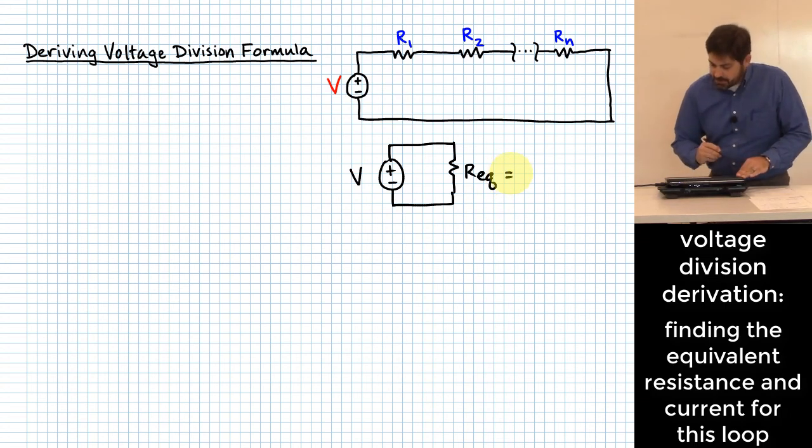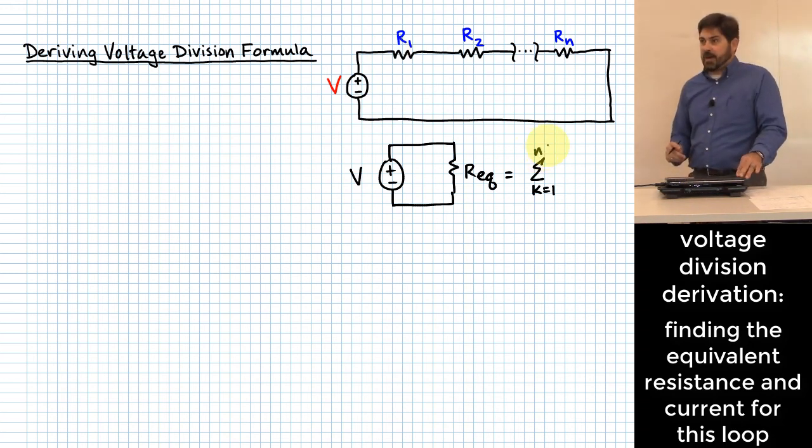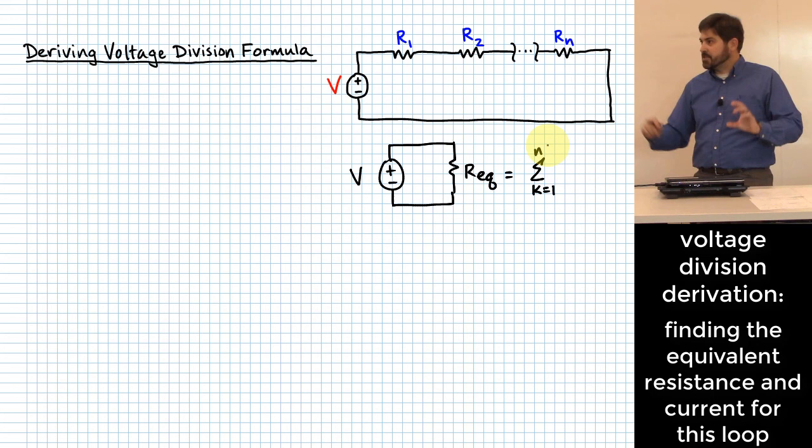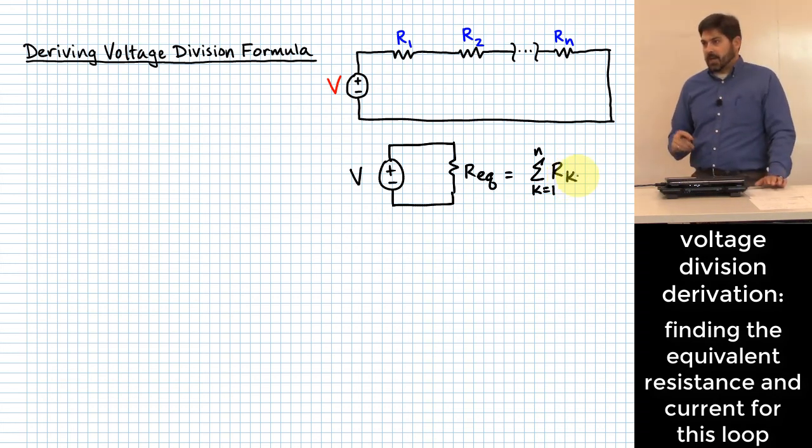Okay, all it's going to be is a sum. This is what we learned, I believe, last time, of whatever an index value is ranging from one end of the range to the other, right? However many of these resistors that you've got. If you number them sequentially, make an index value like this, and you just add up each one of those elements. All right, add up the resistance value for each one of those elements. That's going to be the equivalent resistance.